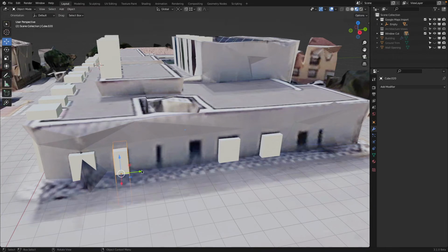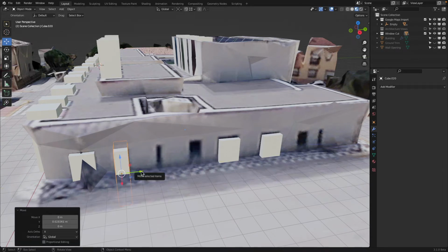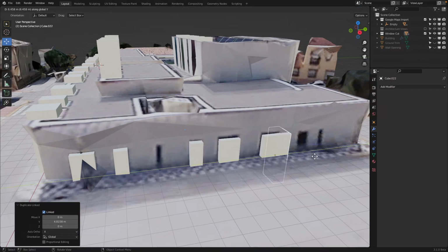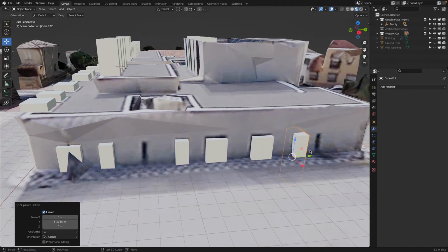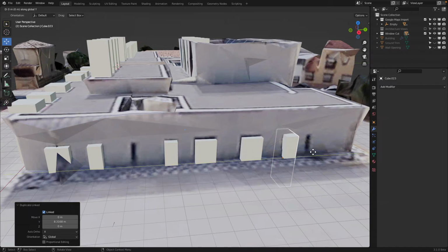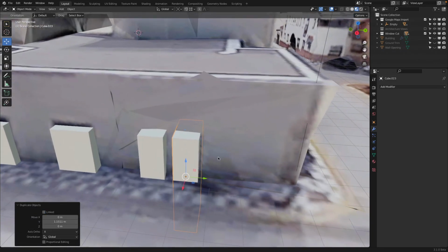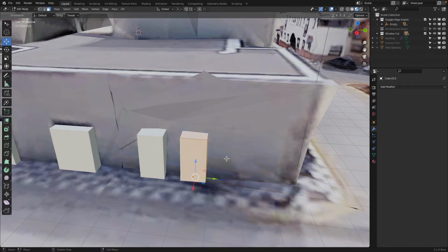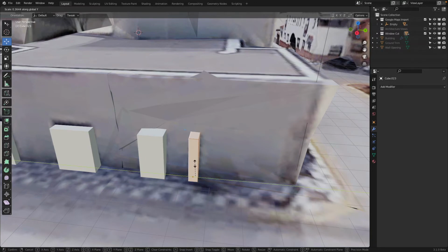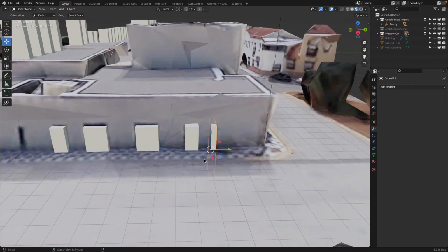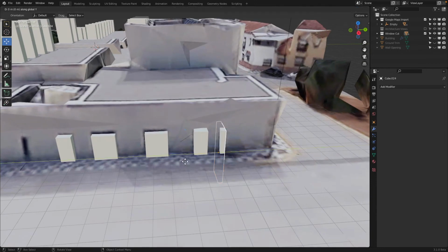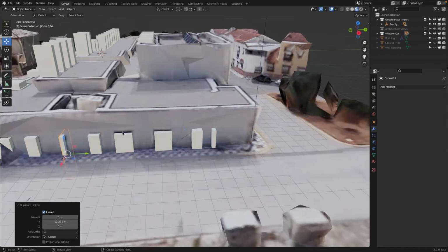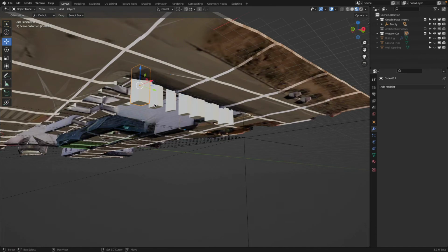Yeah, we're pretty close. And then in Tab object mode, I can move this over. Alt D, Y, Alt D, Y. Yeah, it's okay. Shift D, Y. Try to kind of again center it. It looks like maybe here. Tab, A selected. S, Y and maybe like this. And then Alt D and Y go over. Hello there. So how do we do the bottom part?